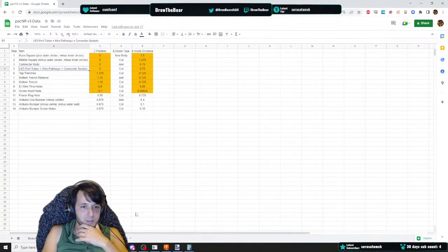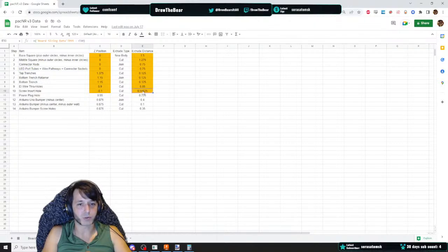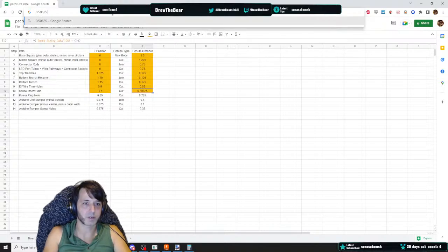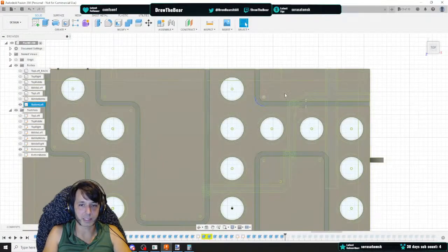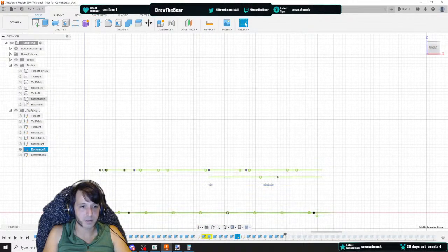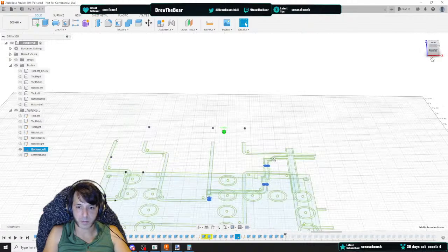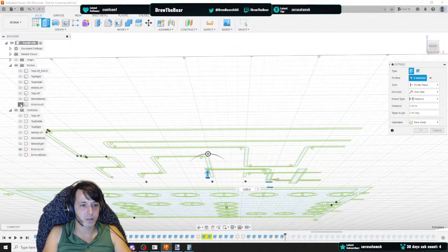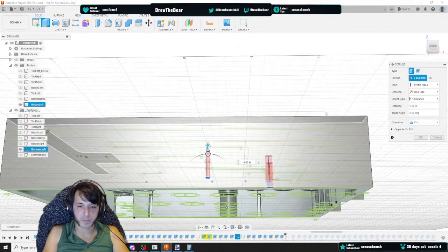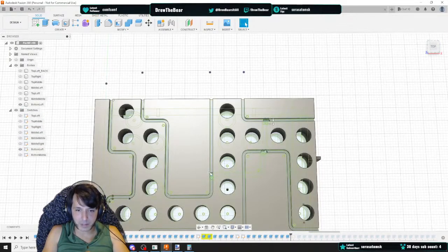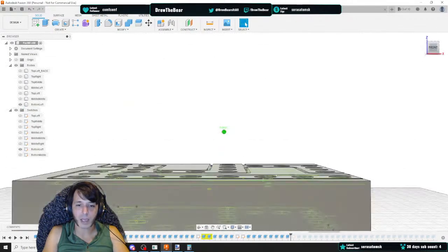Next, L-wire through holes, and then screw insert holes at, let me do, hang on, 0.50625. I'm going to copy that so we can just do that easily. So let's start off and do the screw holes. That's these guys here. And make sure, yep, perfect. We're going to extrude to 0.8. That cuts through. So now you have these holes from bottom trench to top trench in the areas that the trenches line up with.